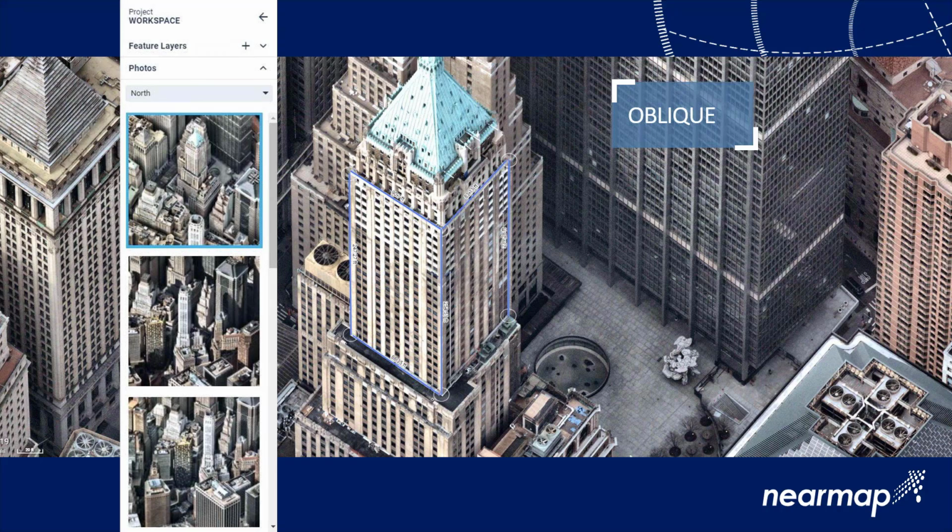And all of these obliques are with our latest camera system, meaning they have a ground sampling distance of 2.2 inches. And the vertical and horizontal accuracy still stands with this content as well. So horizontally 28 centimeters and vertically 40 centimeters. So those are a little bit the types of our 2D content, what goes into it.